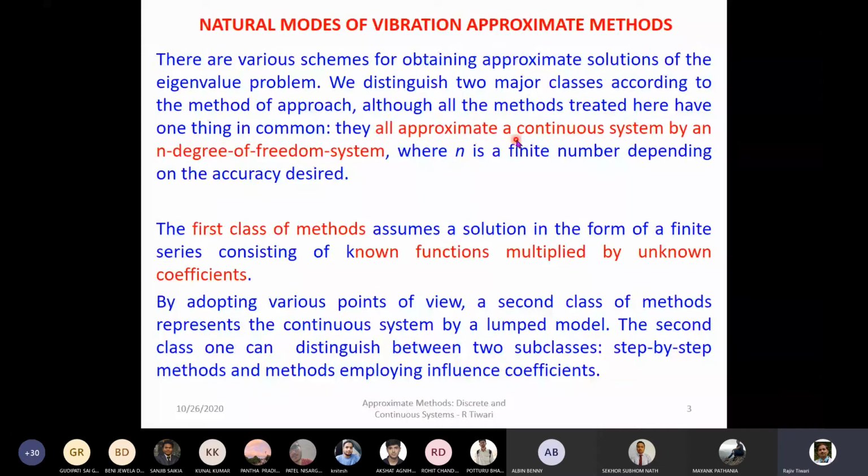We only wanted to enclose some natural frequency, and we don't even know which natural frequency we are enclosing; it depends upon the choice of the eigenvector or comparison function we have chosen. So now, based on the Rayleigh's quotient, we will more systematically develop a method which can discretize the continuous system to an n degree of freedom system. That is the basic crux of the approximate method.